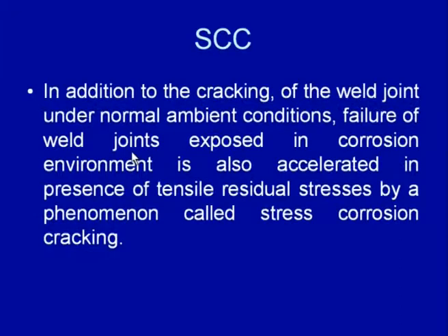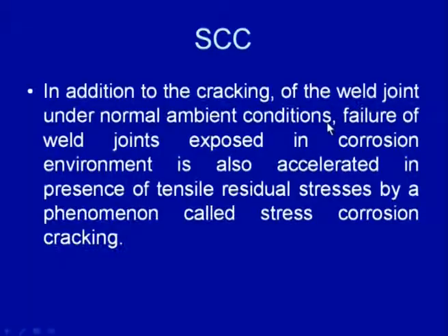Another important effect noticed in the presence of tensile residual stresses is stress corrosion cracking. Stress corrosion cracking is the cracking experienced by weld joints under normal ambient conditions or in a special environment, especially when the joint is exposed to a corrosive environment and is subjected to tensile stresses. Even in some cases when there is no external tensile load, the presence of tensile residual stresses in the weld joint and exposure to a corrosive atmosphere cause cracking, even without the presence of an external load.